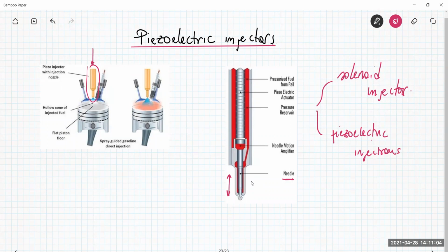So, for example, this slide shows exactly the situation, the cross section of this material, in which we have a stack. This is a stack of PZT, exactly the same construction that I commented on before, with very thin slices of PZT material with multiple mechanical connections. Then a voltage is applied to it in order to make an elongation, a deformation, a displacement or not.